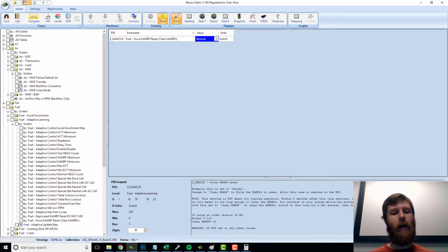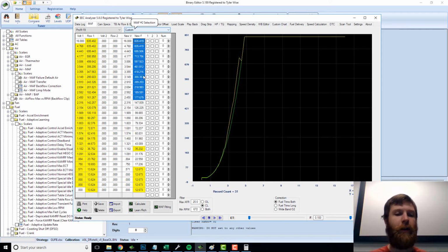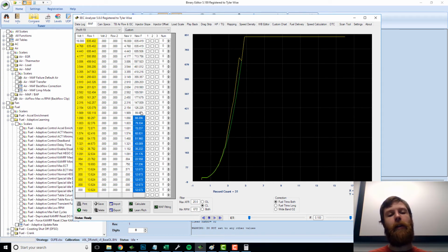And the way that you decide on if you want to work on your slope or your mass air transfer is usually that if you have a scenario, I'm going to go back to EEC Analyzer for a minute. If you find a scenario where just a couple cells here and there pop out at you and it's recommending a pretty substantial change, but in general it's not, that's probably an indication that your mass air transfer has a couple cells that need to adjust. But if you notice as a blanket statement that a whole bunch of these cells in the low area or the high area, whichever one you're tuning, are off, high slope is generally the top portion of your mass air. The low slope is going to be most of the lower cells. And if you notice that as a whole, they're all off by a similar percentage, like we could universally say we were about 3% off all the way through here, then that's usually an indication that you need to adjust your injector slope or your fuel pressure.